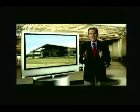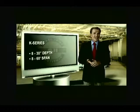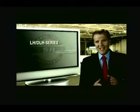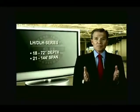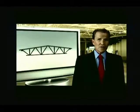The most basic product alone, a bar joist or short span K-series joist, has over 100 standardized designations across 3 load tables. For design flexibility, long span and deep long span series joists can be manufactured with parallel, single pitched, or double pitched cords, and can also be either underslung or bottom cord bearing.